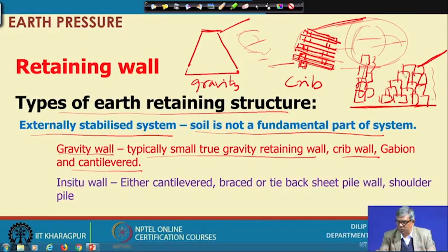So, all together will work like a wall, and this soil will be supported by this. This is also quite flexible, and in hilly areas, this is a very good solution for retaining the rock and soil. So, this is one called gabion wall, and there is another type, that is cantilever retaining wall, that is generally made of concrete, and typically it will be something like this.